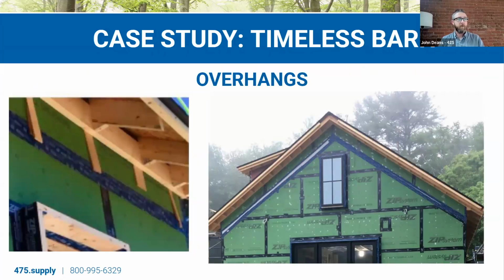A common thing that we had to deal with on this was, well, we're thickening the roof by 16 inches or better. What do we do about our overhangs? So you can see here it was relatively simple. We just built overhangs down on the sawhorses, nice and straight, and then we bolted them onto the side of the building. The building walls were in and out all over the place, so we had to do some shimming, and it was fine. We could change the pitch to make sure that everything was nice and straight coming off the roof. It allowed us to create whatever overhang we wanted, and keep that slimmer profile that fit with the original vernacular and the New England vernacular that surrounded the neighborhood.